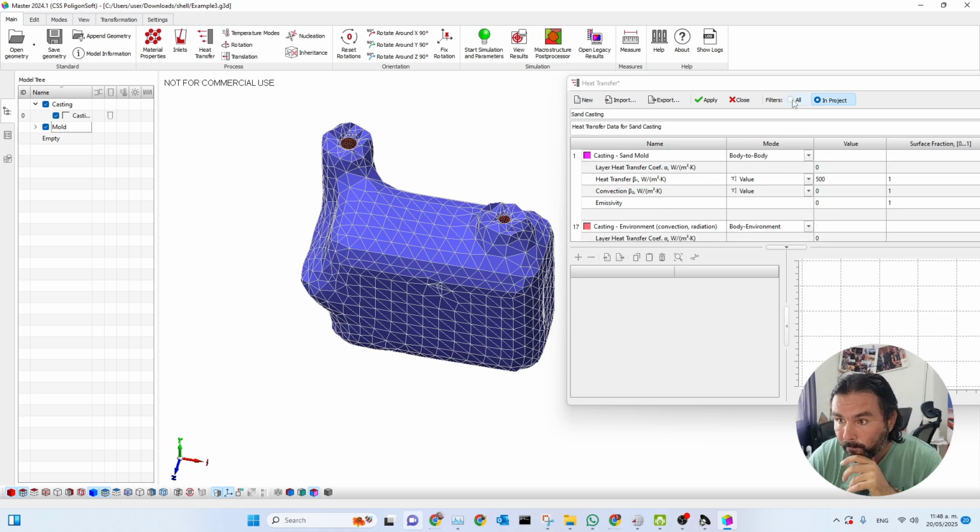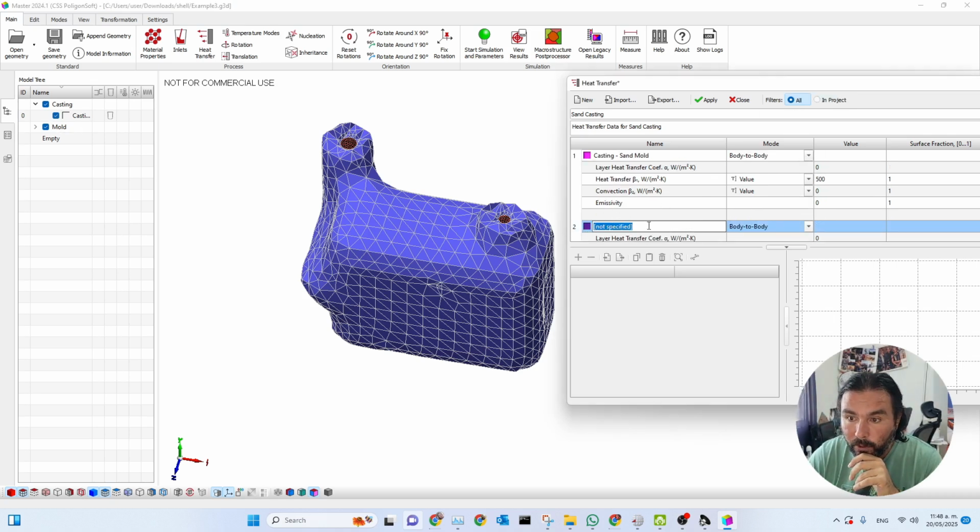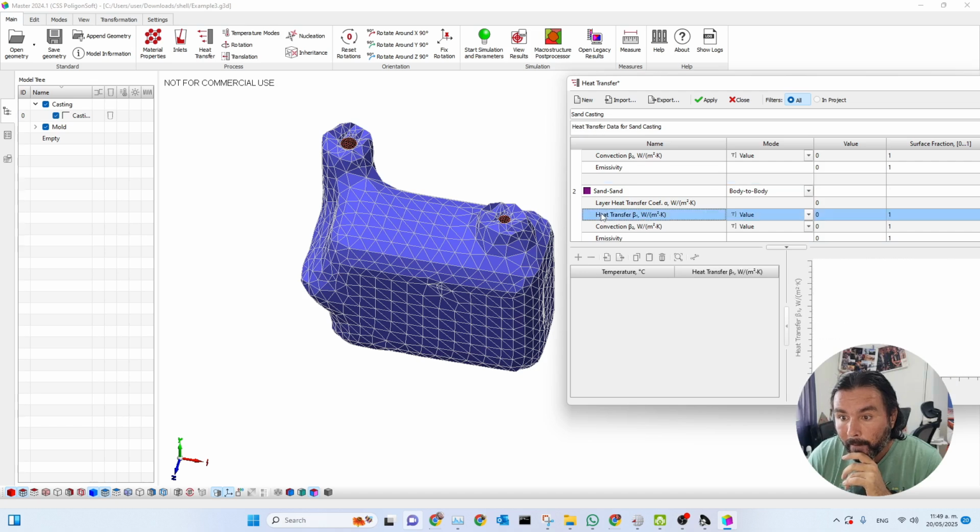First, let's make a second index. Let's say index 2 for a heat exchange index between sand and sand. The heat transfer parameters will be like the parameters of an ideal contact. The material, in reality, doesn't have any type of contact. It's the same material. That's why here we put the heat exchange for ideal contact, which for sands corresponds to 10,000. We've created that here.